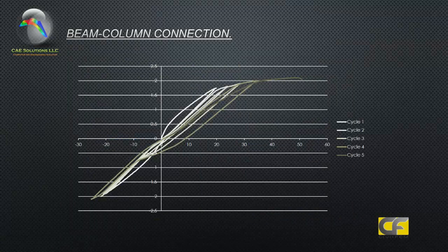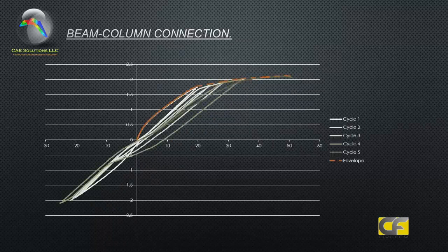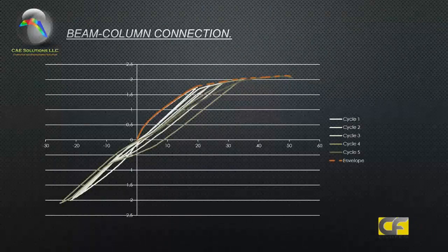Okay, so now let's see that in this example we made 5 cycles. Okay, 5 hysteretic cycles. There you can see the force-deformation curve for each of the cycles. In the next slide, we're going to see that, starting from the cyclic behavior, we have the cyclic envelope.